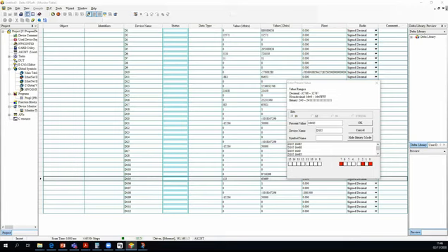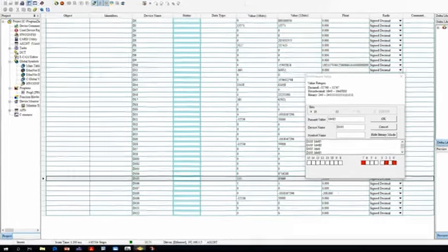But if you want to do positioning, then you absolutely have to enter the motor nameplate, to do an auto tuning, to set the encoder details into the drive, and then to set the drive to run in field-oriented control for PG cards. So let me see if I can just show this.